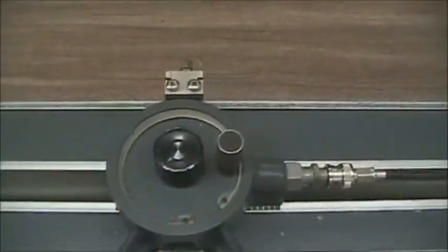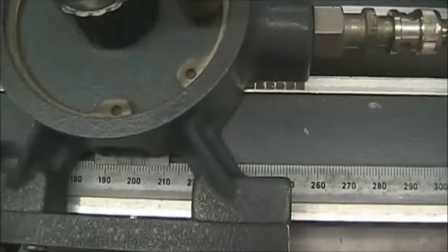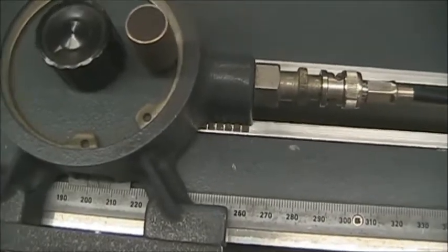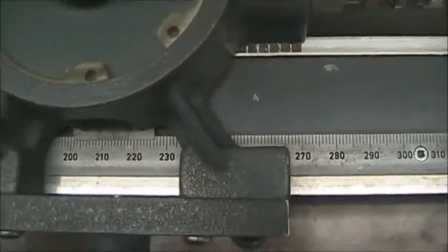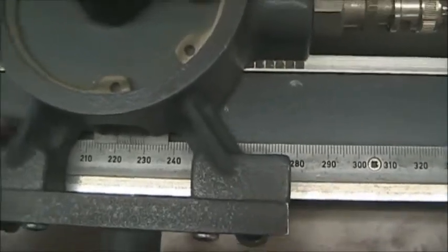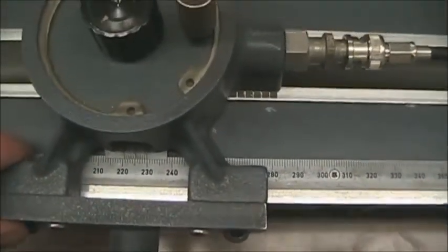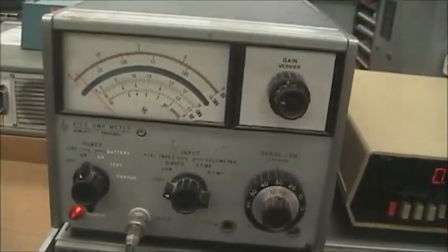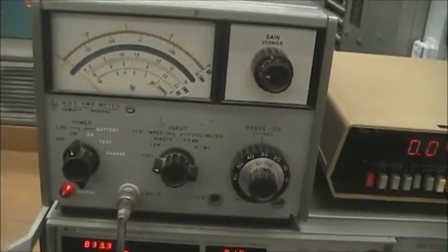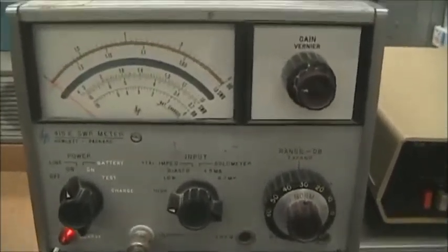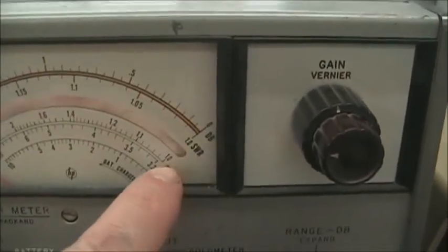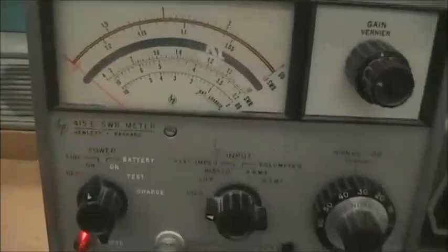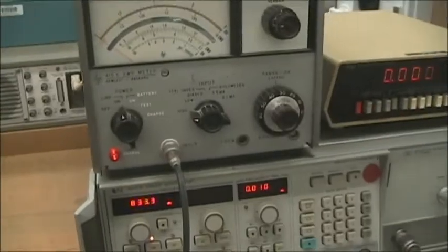After we've done that measurement, so you can see I have a reading, I'll move it to a certain position, and normally I just use the numbers on here, 200, 210, 220, and take my measurements. I do try and find the peak and the null. You can see as I move the carriage, it goes through a range of values. Of course, for an open, the VSWR is maximum. So if you look at our VSWR scale, this one is the one we're using right here. It's going from 1 to more than 4. Of course, with an open, it will be infinite.